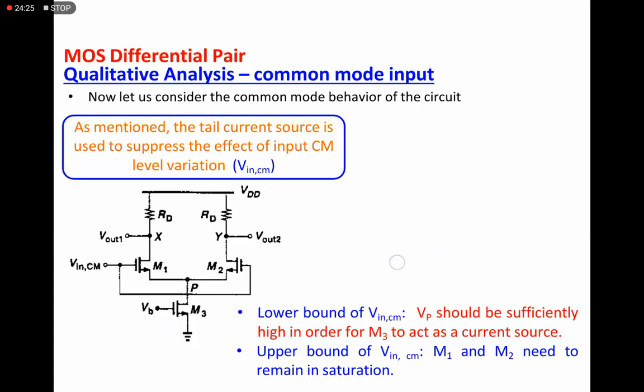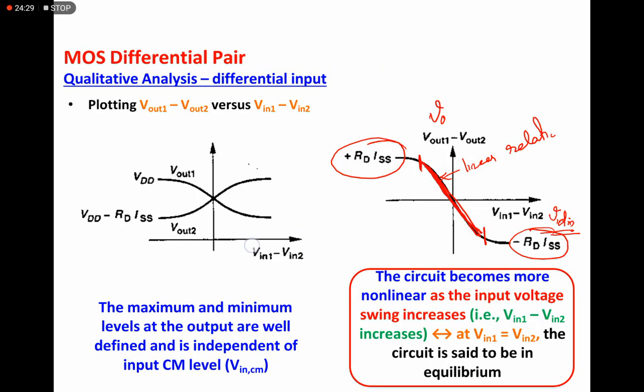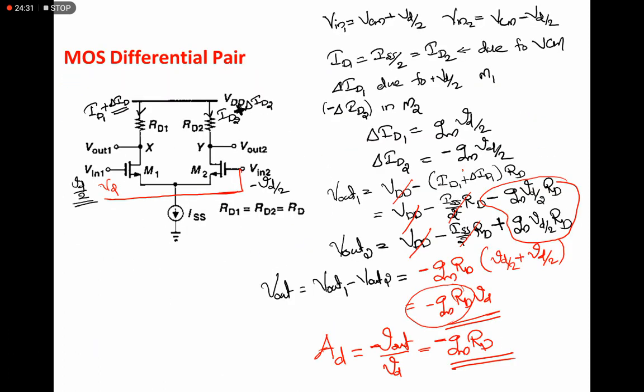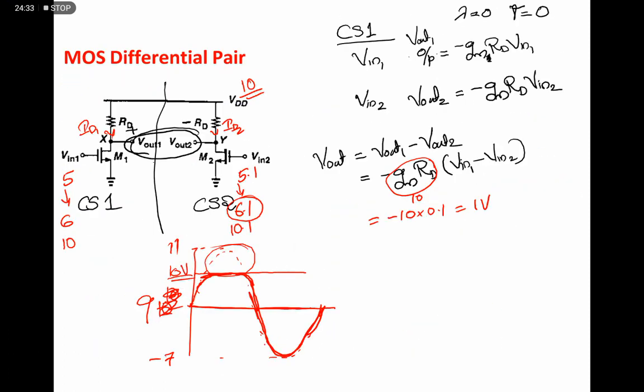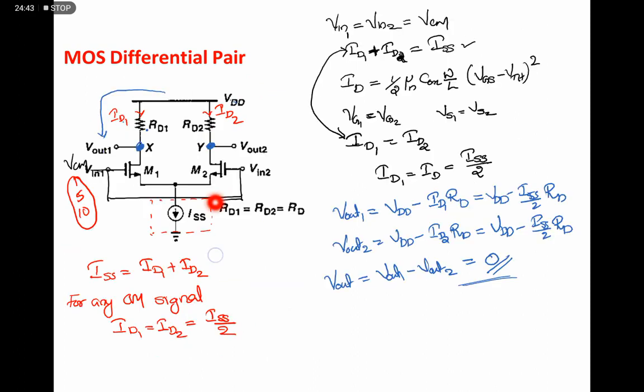And similarly, for the common mode signal VCM, earlier we discussed that when the common mode signal is varying, in this amplifier circuit the output may clip off or distortion will be there. But in the actual differential amplifier with the tail current source there, the common mode signal is independent.